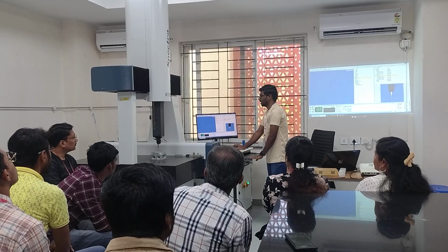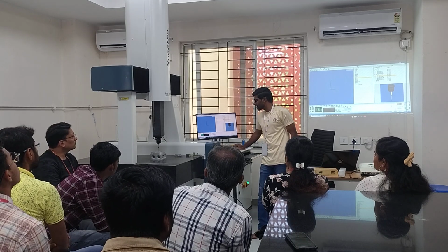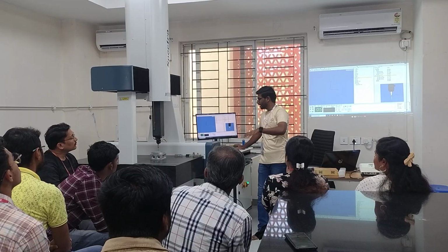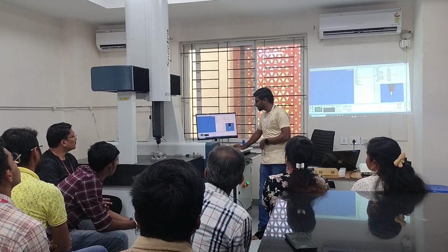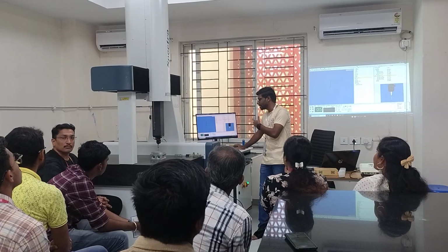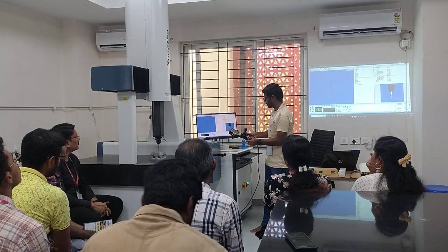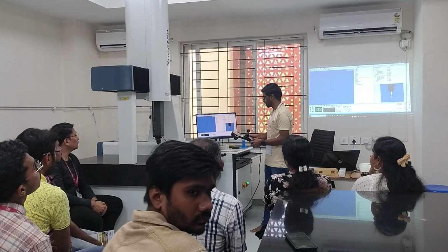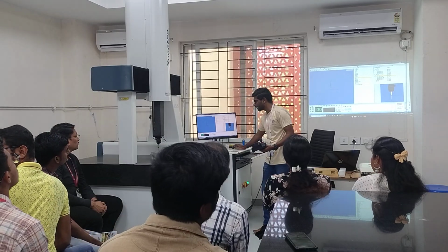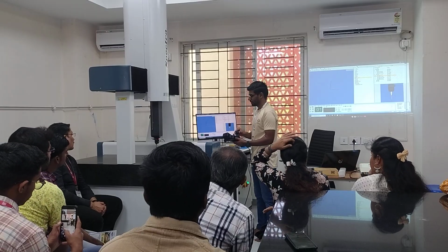I'm sorry, I have made a mistake. I have taken 5 points, but I have not selected a plane here. I'm supposed to measure a plane, right? So what kind of object or form you are going to measure has to be selected. Definitely I have to cancel all of them. So I'll select plane here because I'm going to measure a plane. Then again I will have to take 5 points.